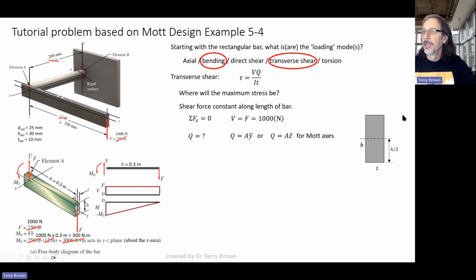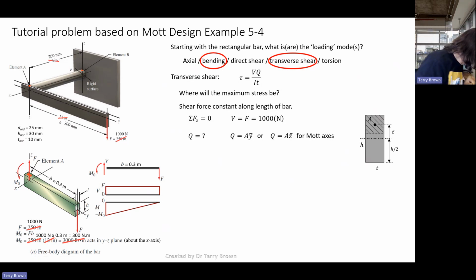All right, so if we've got our cross section here and we want to know the shear stress, so this transverse shear that we've got here, looking at me in the picture, if we push down here, we get, it's floppy, right? Because the pages are sliding relative to each other.